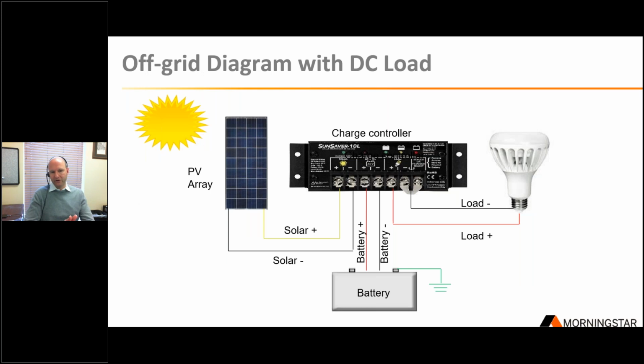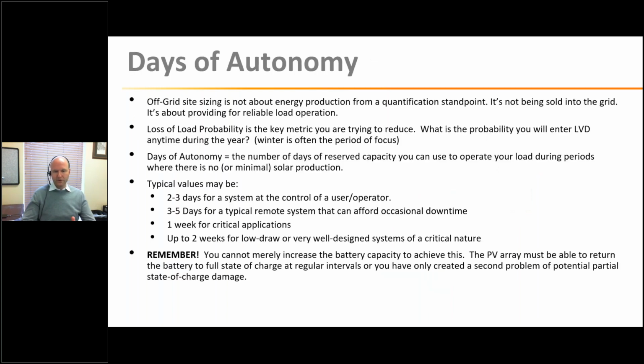And here's a quick example of our SunSaver battery system. You've got a SunSaver solar charge controller and the lighting control, and then all those timing circuits and everything are built into the controller so that you can manage it automatically, unattended. Okay, so what leads to LVD is, of course, lack of battery power. You don't want to damage the battery, and you're also at that point just out of juice. So you have to disconnect the load so that the system doesn't go down completely.